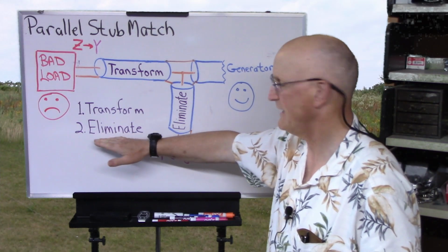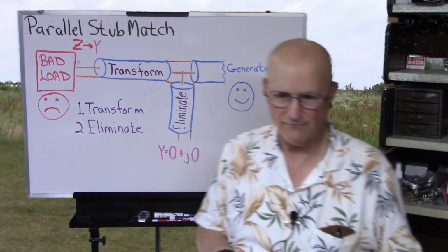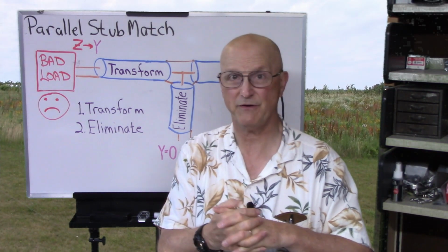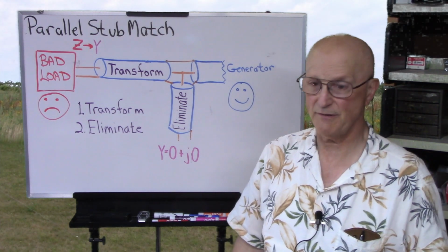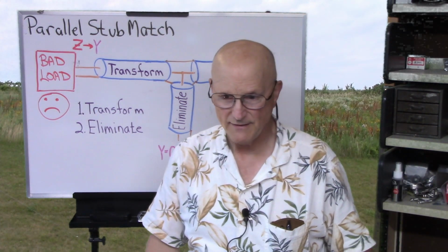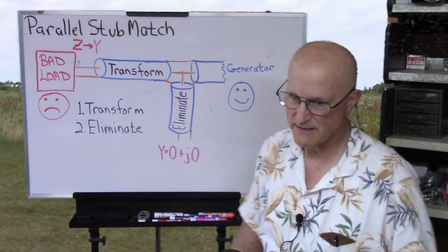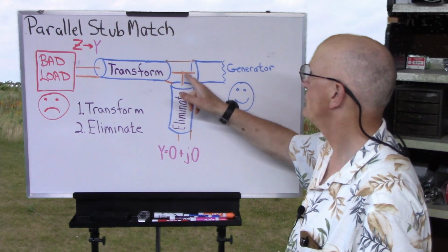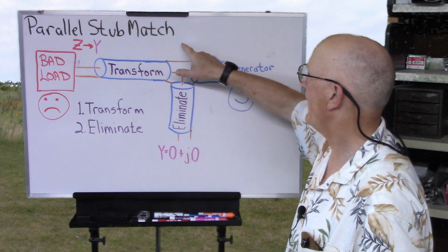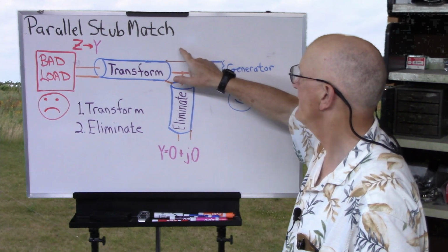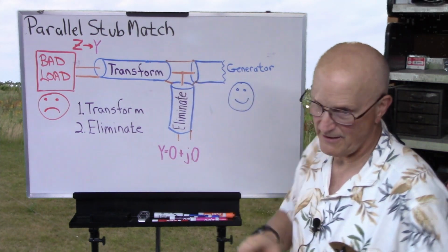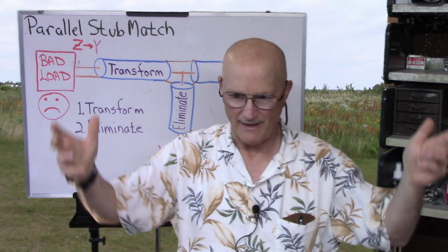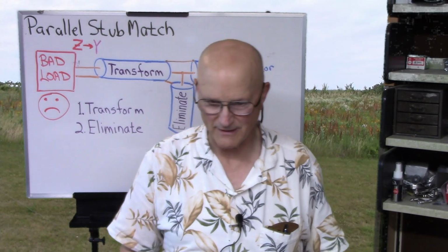This introduces the need to eliminate. In the 2nd video in this series, I addressed the issue of eliminating the reactive portion of an impedance. This same principle applies to admittances. This is where the stub steps in. The stub introduces an opposing reactive component right at this point to eliminate the reactive component of the admittance that is being presented here. And what are we left with? The purely conductive real portion, and everything is great and we have a wonderful SWR.